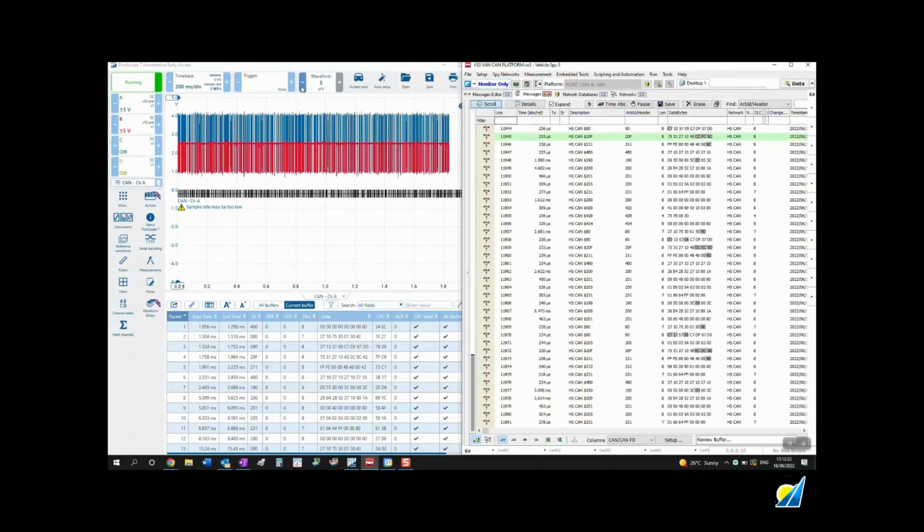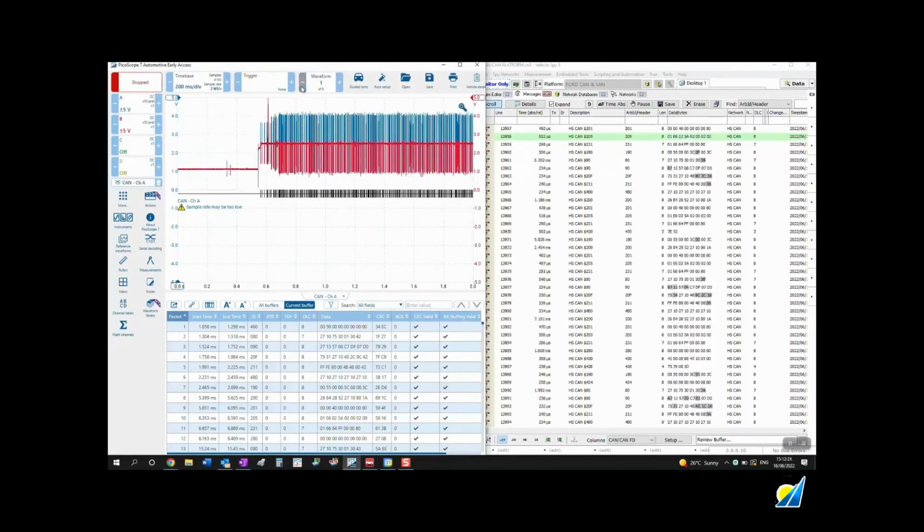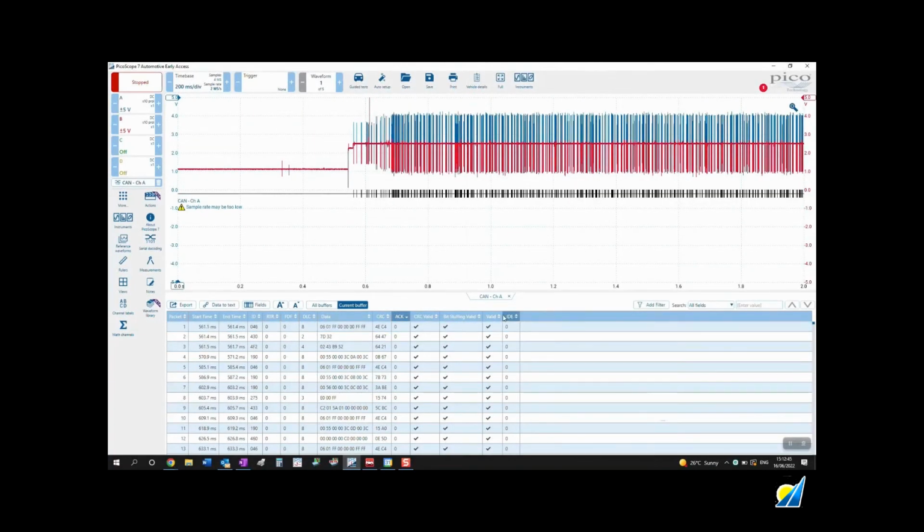And if we pause Pico and go back right to the start there, quite often you may see an error here or no acknowledgement, because often ECUs wake up at the wrong time or different times. That is all good. So we look for an acknowledge. Let's go full screen here. Or valid and invalid. No, there's nothing. So everything decoded successfully there, which is cool.